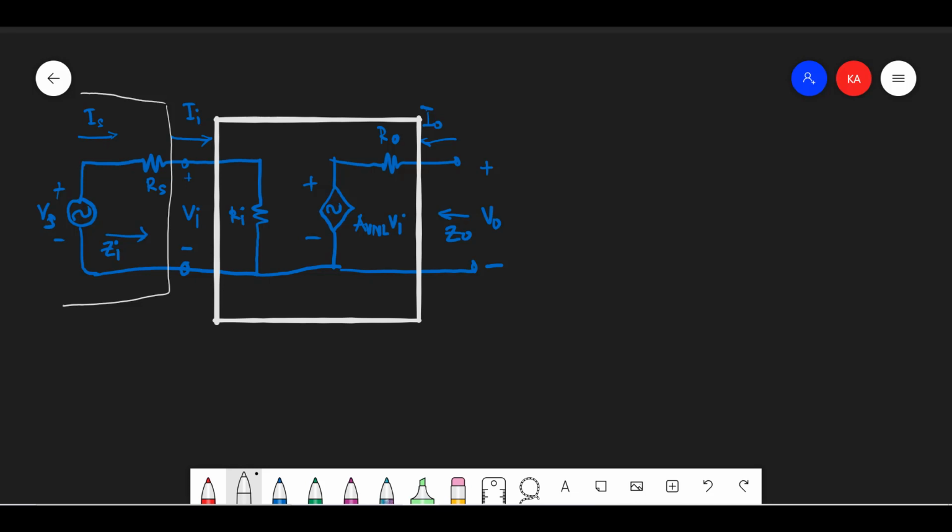If we put the source resistance Rs and Vs at the input of the BJT, what happens in the two-port approach? Remember that if we didn't connect the input voltage to a source resistor and source voltage, the input voltage is simply Vi.